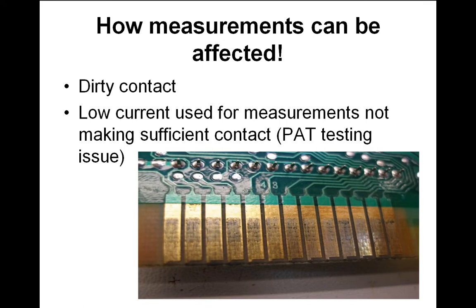And again, with experience, it sort of comes to you slowly. What I tend to do is, when I've got a meter and I don't get a reading, I start scratching a little bit with the probes. You've noticed the probes are quite pointy as well. They've got quite a vicious pointy bit right at the front. So I scratch a little bit to make sure that there really isn't a voltage, or anything present, or if I measure for resistance, to make sure I'm getting a real reading.